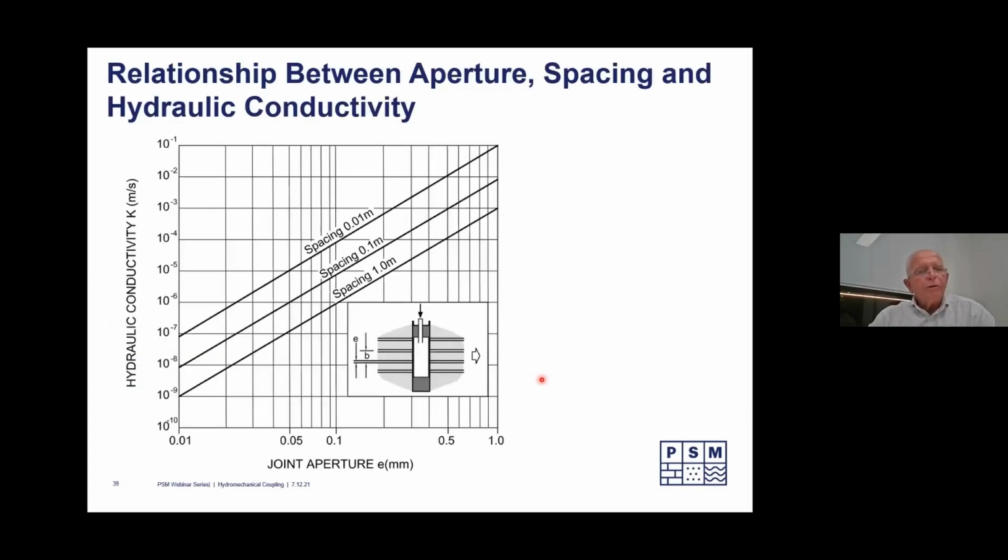This is a very useful little tool I've found, and it's a plot of hydraulic conductivity versus joint aperture, so how wide the cracks are. It's a simple system here. It's 4 parallel structures, open a certain amount. This really emphasizes the importance of aperture.